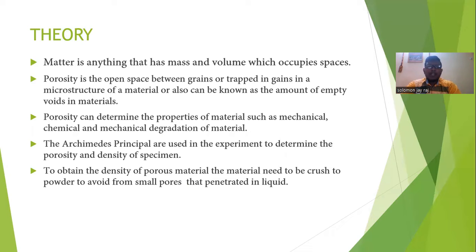In this determination of porosity and density of our specimen, we are using the Archimedes principle. And to obtain a porous material's density, we need to crush the materials into powder, due to the small pores in the material that can be penetrated by the liquid.